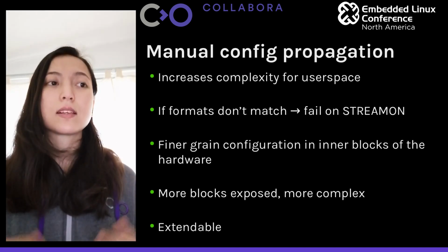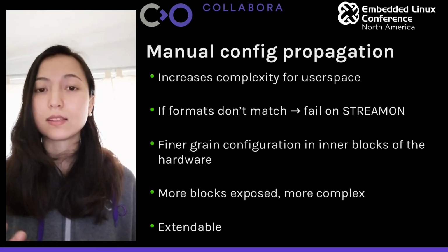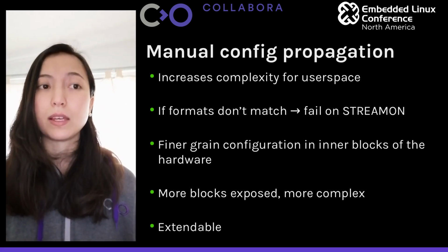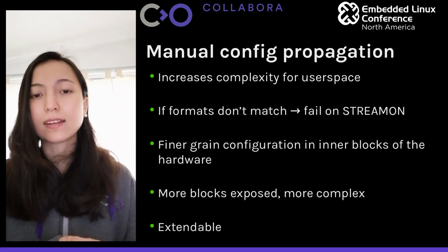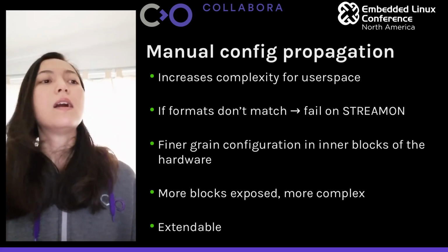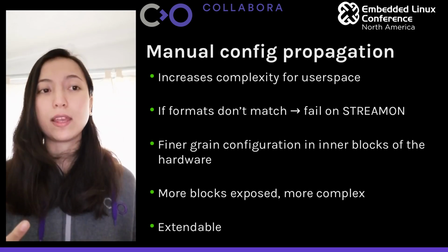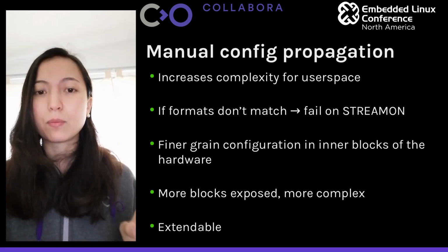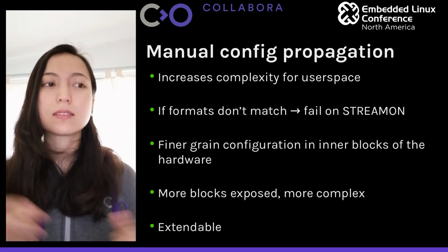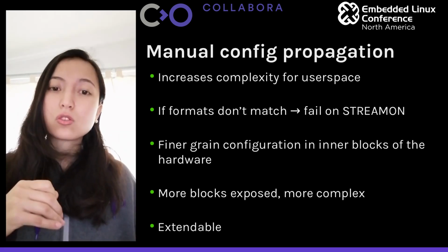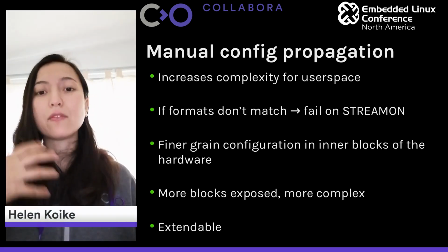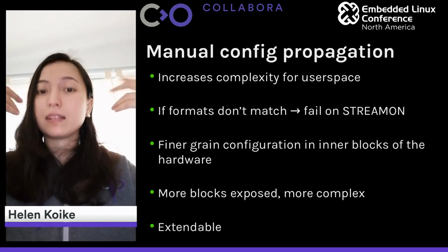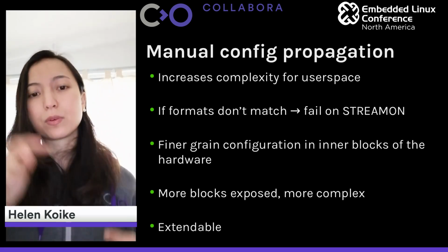As you can see, this increases a lot the complexity for user space since it needs to perform all those configurations, and if formats don't match, when you try to start the stream, it will fail. On the other hand, it provides you a finer grain configuration in the inner blocks of the hardware, and I'm going to show you an example when we need this. But also, the more blocks that we have exposed to user space, the more complex it becomes, since we have more points where we need to perform the configuration.